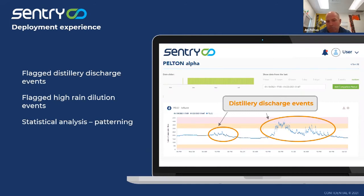And as far as maintaining the units or having to mess with them, almost nothing. We had to do very little. Frankfurt's bar screens are not great. I believe they're 3/4 inch, maybe 1 inch. So occasionally they were shaking rags or debris off of the probes, but there are no calibrations or any reagents or anything that need to be changed. The probes reach steady state and you basically leave them alone.